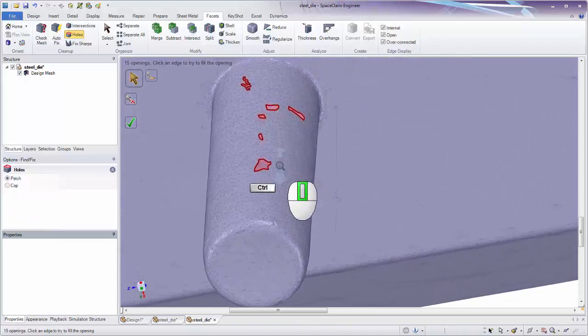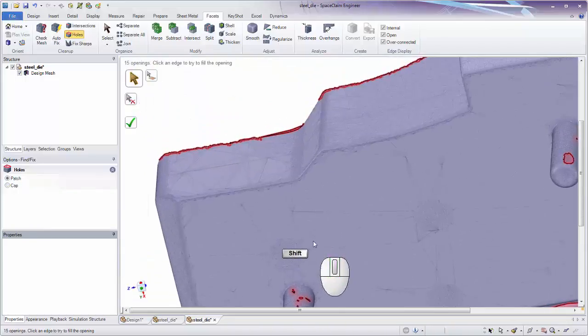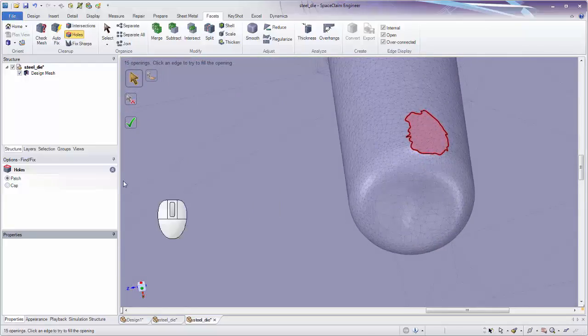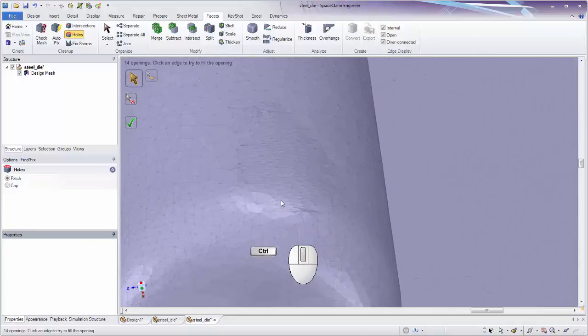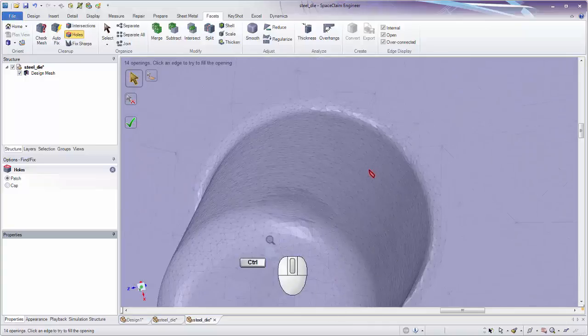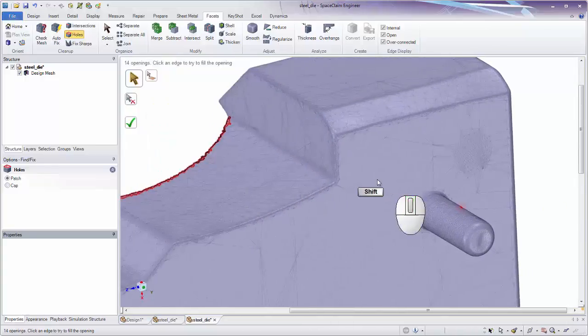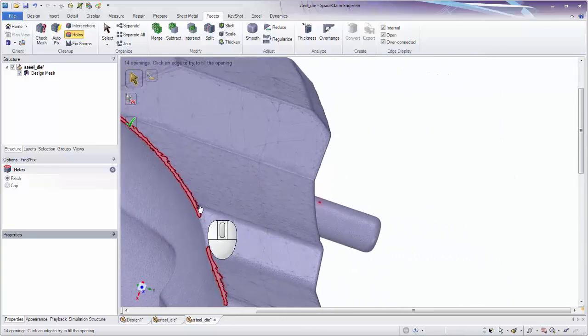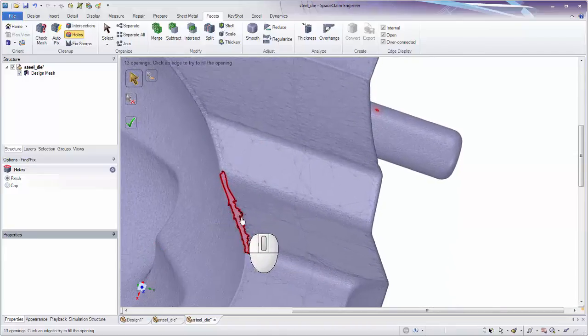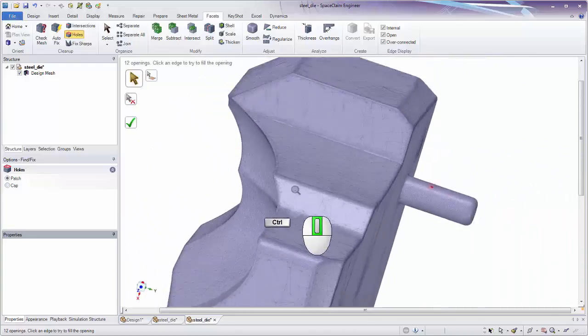And so we typically recommend looking around the model, seeing which repair should be used. For example, this is part of a cylindrical face. It should be patched in. And we can see here it makes that nice curved patch using the surrounding facets as guides. Same thing with rounds. We typically want rounds to follow the curvature that's there, remain tangent to the other faces. We could go ahead and click those.